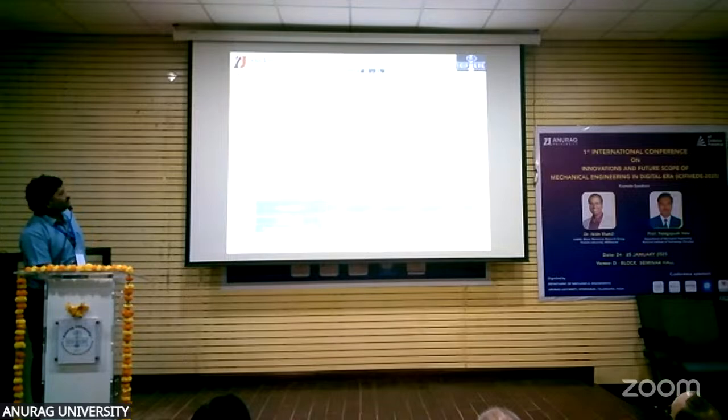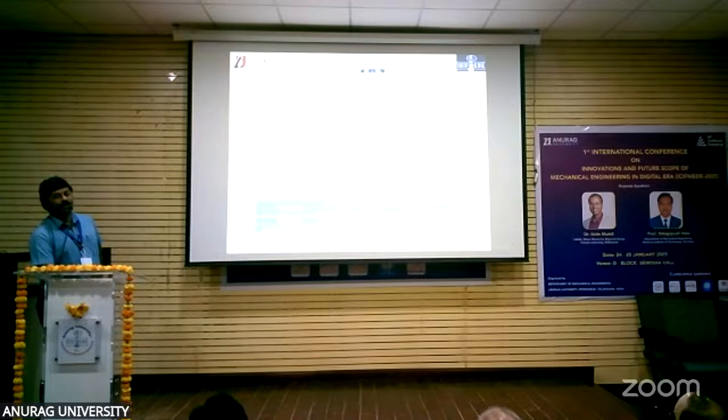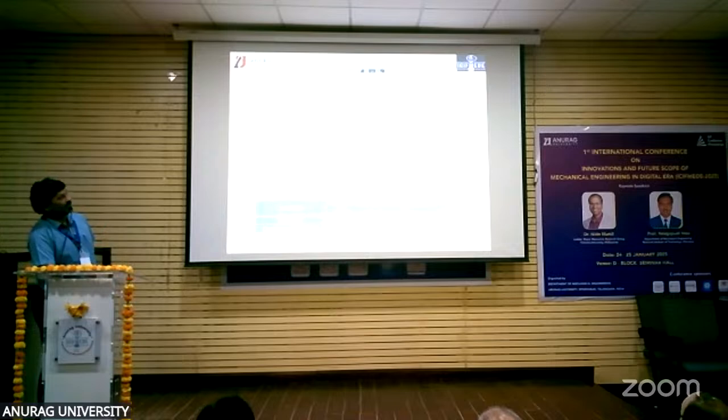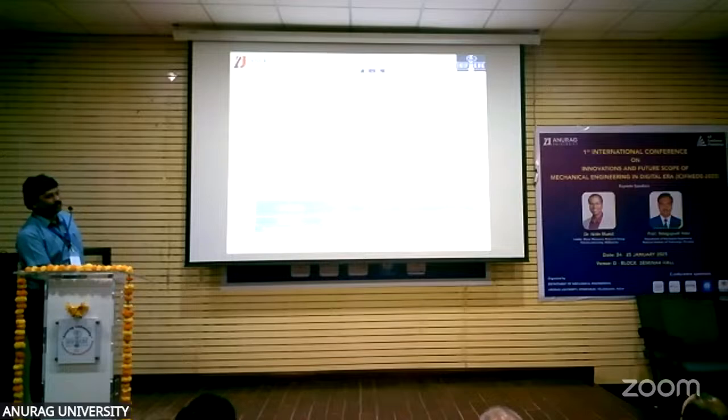And the results. After doing the Taguchi method, grey relational analysis and TLBO for the weld strength of the joint, I took the three optimization techniques. The optimal parameters found by TLBO are 2.5 bar, weld time 3.5 seconds, and amplitude 60 micrometers, achieving a weld strength of 27.9 Newton per square millimeter. If you observe, Taguchi is giving around 22 to 23 Newton per mm square, GRA is giving 25 point something, and TLBO is giving 27.9 Newton per mm square.